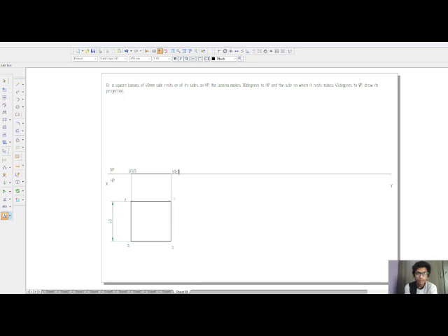Now, we will determine the surface inclination. Here, the lamina makes 30 degrees to HP. So, we will take a normal line and incline it to 30 degrees to HP. And using the angle between command, we will measure the angle.